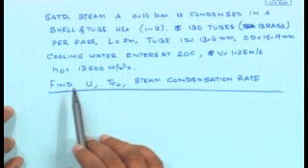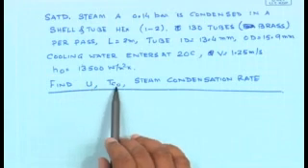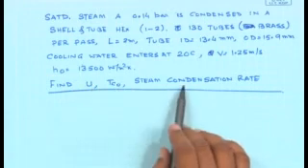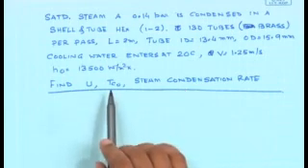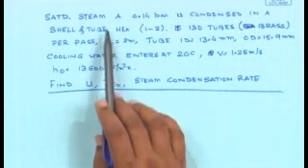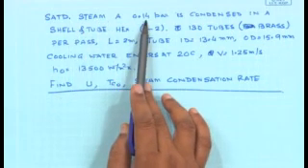What we have to find out is the overall heat transfer coefficient, the temperature of the cooling water at the outlet, and the rate at which steam gets condensed in this heat exchanger. Needless to say, we know the temperature of the steam, since it's saturated and the pressure is provided.